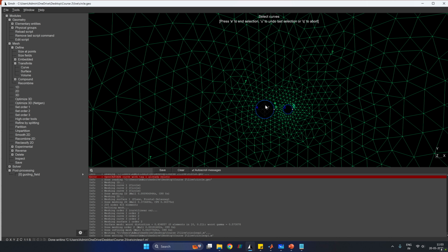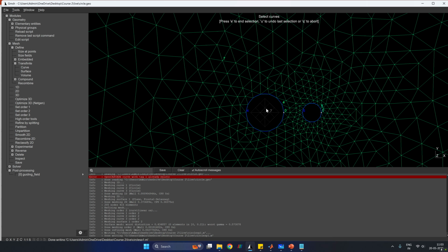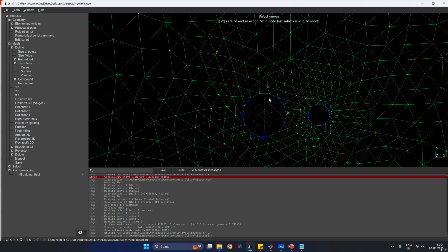A liquid-liquid interface is more like a stress jump or a force jump. Navier-Stokes is a momentum balance, so you could also think of it as a force balance. Rather, it starts from a force balance, you could say. That's one way of looking at the derivation. And so the terms which you get on the interface, in this case the secondary term is the heat flux, or the flux, and in the Navier-Stokes case it is the stress.